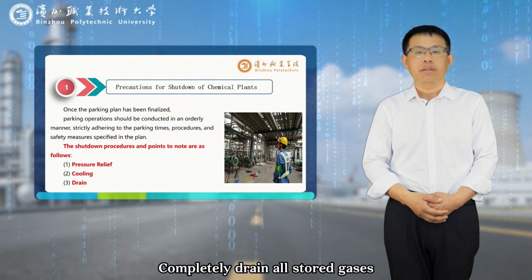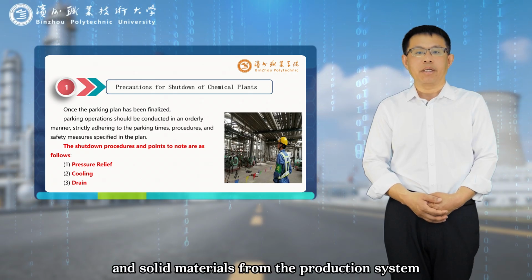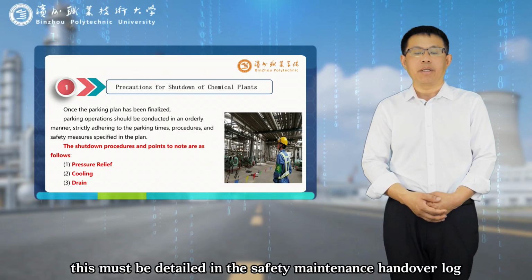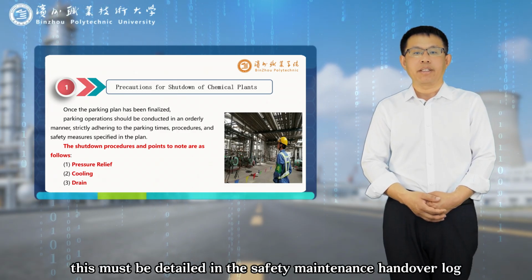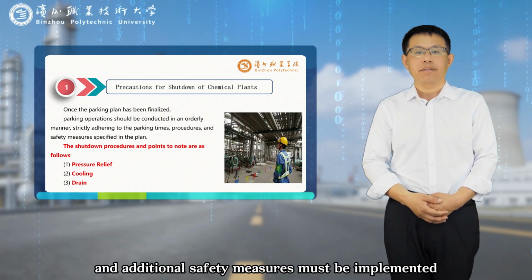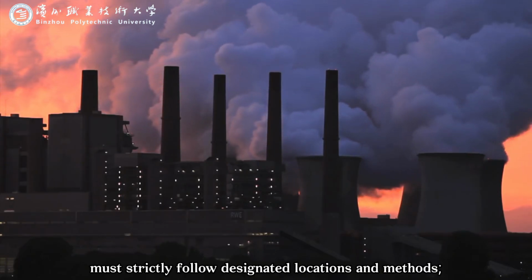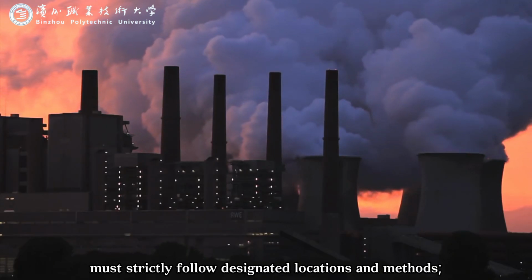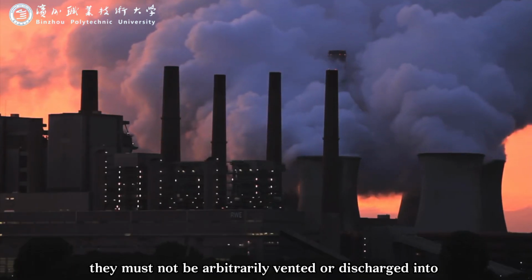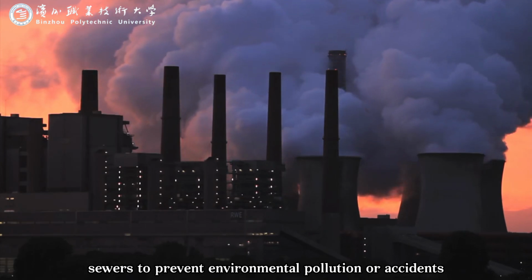Third, completely drain all stored gases, liquids, and solid materials from the production system. If materials cannot be completely drained, this must be detailed in the safety maintenance handover log, and additional safety measures must be implemented. The discharge of residual materials must strictly follow designated locations and methods. They must not be arbitrarily vented or discharged into sewers to prevent environmental pollution or accidents.